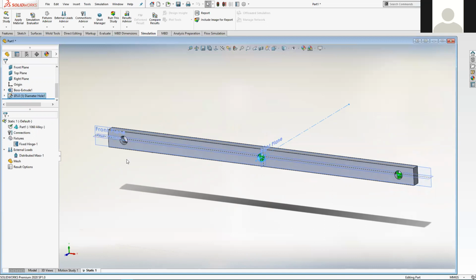And the reason I'm making a point of that is, don't assume that these simulations that we're setting up, well, don't assume anything, I suppose, is what I'm trying to say. If you were to run this experiment in a lab, you wouldn't have to worry about gravity, as in you wouldn't have to switch it on. But these simulations don't occur in the real world. So you have to make sure that all the forces or gravitational constants are actually applied. So we're going to have to do that.